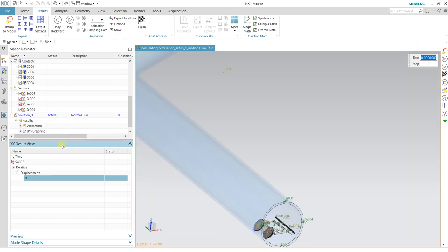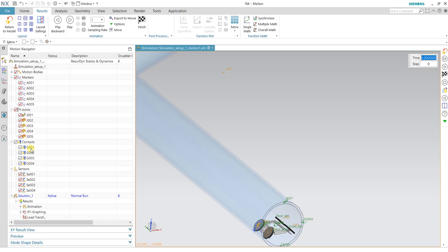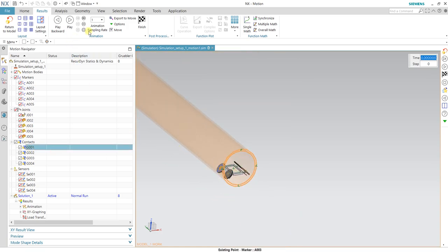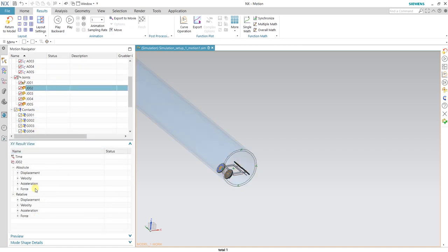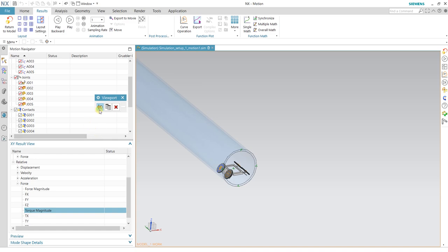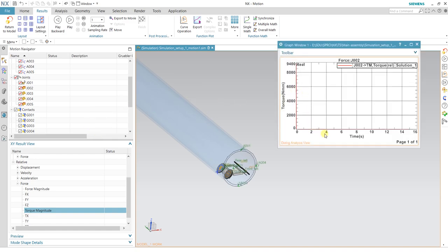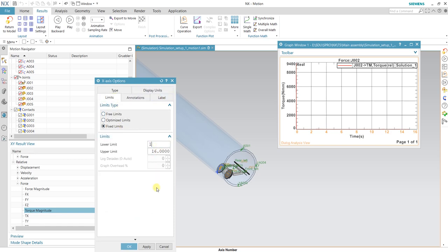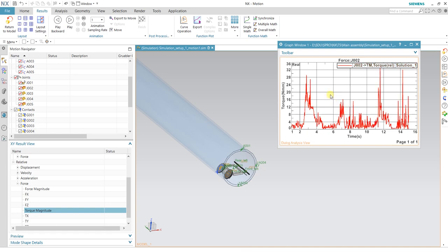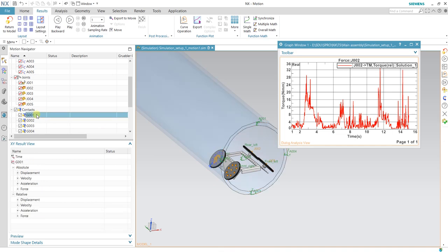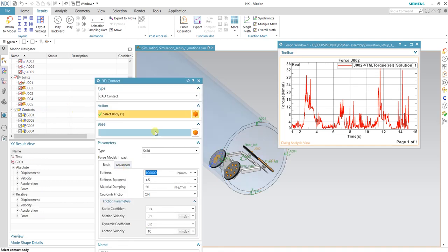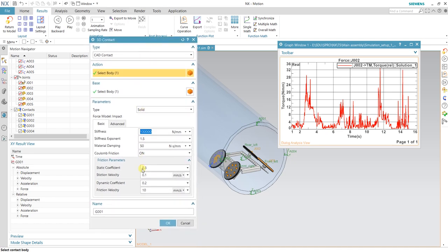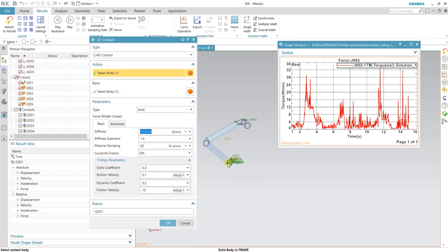Now let's see how we can fix the torque. The torque is really noisy because of the contact, because it is actually slipping a lot. If you look again, let me limit the time. Here you see that the torque is very noisy, and if we average it like this, we probably don't get a good number. The problem is the stiffness and other parameters like damping in the contact.